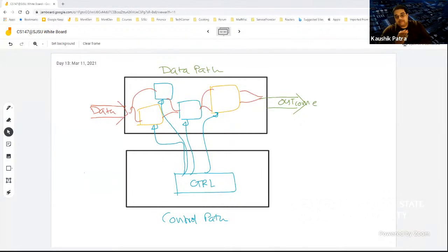And we have seen that the main theme is that we treat separate classes of the R-type functions, like the logic class, the arithmetic class, and special ones like the shift amount operation. We designed the different data paths using this ALU and register file. Then at the end of the day, we superimposed these data paths on top of each other and tried to find out if there is a conflict between the incoming data onto a specific data crunching resource like the ALU or register file. If there is a conflict in the incoming data, we resolve that conflict by placing a multiplexer to select which data to pick up for that specific instruction. So that's the general theme.